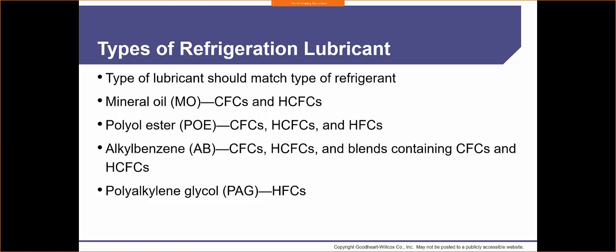So most manufacturers now are saying, don't worry about the flush, because there's potential for more damage than good. Whatever mineral oil is on the sides is perfectly fine. But we're not going to just take mineral oil and POE oil and dump them together and mix them. So we're trying to keep those two things separate.